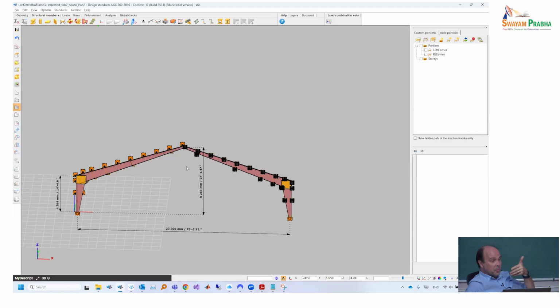And from the buckling shape point of view, this is a 3D problem, and this is full of torsion. The buckling mode is always the weakest part of the sections. That's what very many engineers say, that, oh, I don't need this complicated software, I'm always designing in 2D. Yes, but do they need to perform an LTB check? Probably, yes. Resistance is controlled by the out-of-plane.